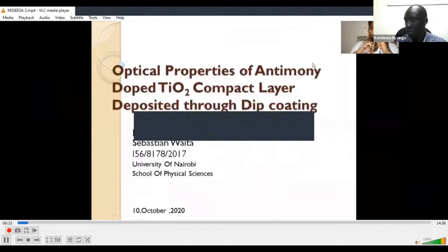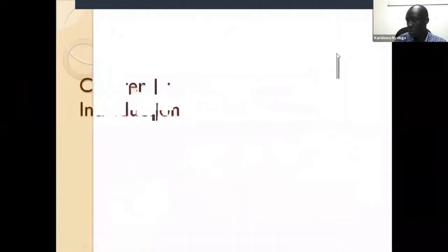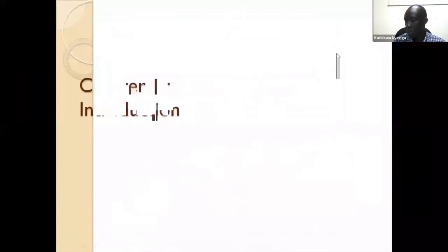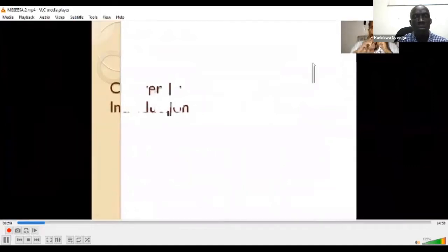First, to understand what I'm doing, you have to understand the background of my research. Currently, there are two new types of solar cells: perovskite solar cells and dye-sensitized solar cells. Both have shown to be quite good at collecting solar energy, with perovskite solar cells being far better, already surpassing conventional silicon solar cells. The current architecture for perovskite solar cells is something like this. It's called the mesoscopic perovskite solar cell.